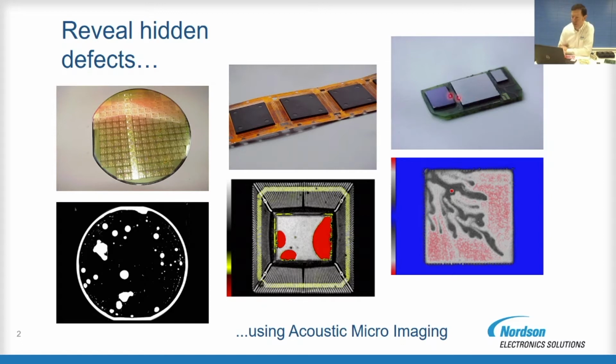Another bad one. So on the right we have a flip chip device, and if we image through the flip chip to the underfill interface, this is the kind of image that we expect to see. In this case there are a few things going on as well. You see this red dot, there's a void trapped in the underfill, and also there's some contamination. You can see the flow marks where they've probably injected it from this corner, and maybe flux or some other contaminant has got in with the underfill, and we're able to detect that as well.